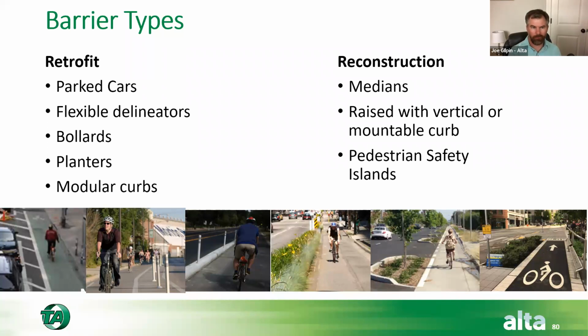I think FHWA and AASHTO say like 1.5 feet to 2 feet is kind of on a lower level street, plenty for what they consider objects not being in that space. So that can be compatible with providing a lot of these barriers for bikeways.